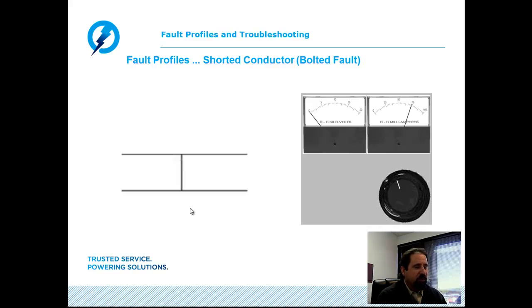Now, the problem when we're using high voltage technique, if we're doing a basic high potential test, is we may not detect that we have a bolted fault on the circuit. In essence, what may happen is as we start to try to apply voltage to the short circuit, what we will basically see is the voltmeter will stay at rest.